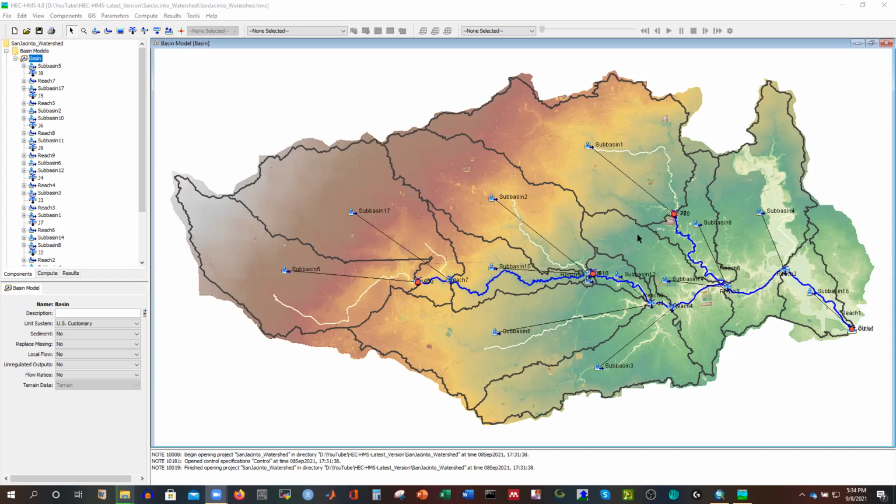I think we have 13 sub watersheds. So I have to prepare that shape file. I'll extract that shape file. I already mentioned that one, right? The previous version of HEC-HMS doesn't have that, but in this latest version we can export that shape file because we created this shape file from DEM. So we have to use this shape file to calculate basin average precipitation.